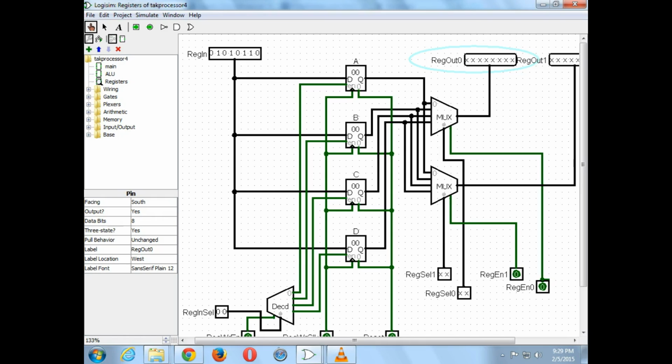So since the clock transition, we store the input we have right now because it transitioned from 0 to 1. Right. But you're saying when it's transitioning back to 0, and we've already got that. No, it doesn't even have to. Once it becomes a 1, it's not going to change, because the signal to change the content of a register is the low to high, or 0 to 1, transition, which can only happen once per clock cycle.